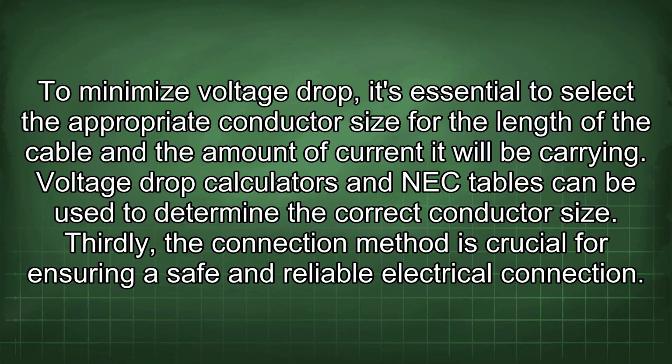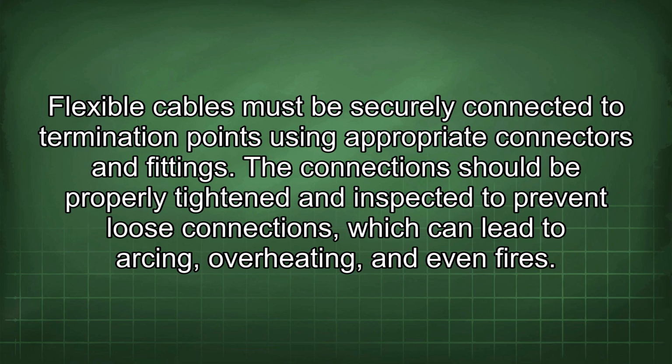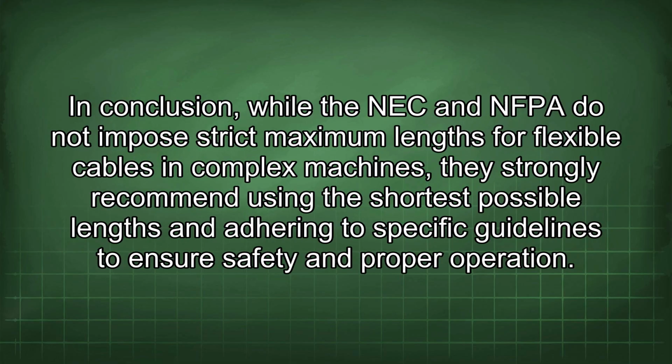Thirdly, the connection method is crucial for ensuring a safe and reliable electrical connection. Flexible cables must be securely connected to termination points using appropriate connectors and fittings. The connections should be properly tightened and inspected to prevent loose connections, which can lead to arcing, overheating, and even fires.